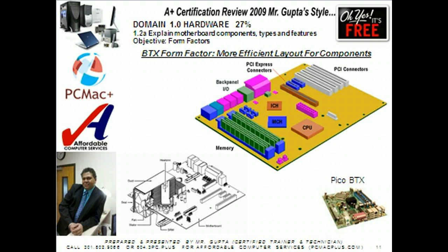Then came the BTX. The BTX form factor motherboards are incompatible with most of the ATX form factor cases and vice versa. In particular, BTX motherboards are flipped compared to ATX and mount on the opposite side of the case. BTX motherboards were expected to dominate over the conventional ATX boards in 2005. There were three reasons for making the change from the ATX form factor to BTX: general cooling deficiencies, the noise generated by cooling, and the more sensible layouts of components to enable smaller systems.